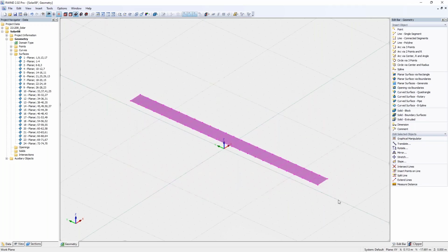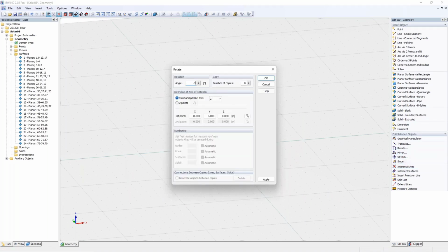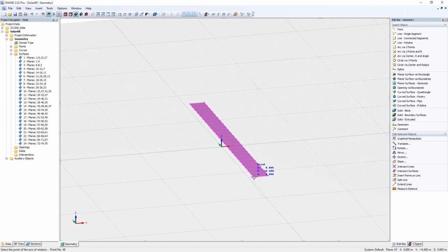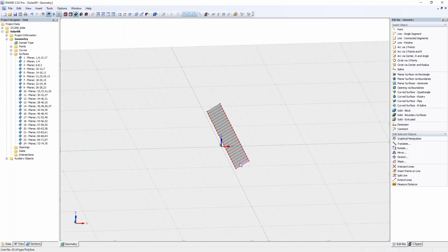And then I want to rotate them a bit because usually they are not laying horizontal. So I'm marking everything, hit the rotate button, and I want to have it minus 30 degrees, no copy. It's the y-axis. So of course I want to rotate them into the wind direction. And since I moved them already, I have to pick at least my node in here. It's also available only for Z, and then they will be put in 30-degree angle into the wind.